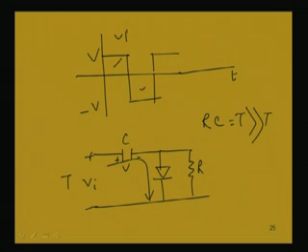Now, in the other half cycle, the negative half cycle, what will happen? In the negative half cycle, this point is negative, this point is positive. Now, this was already V, now again a V. So, across these 2 points, if we consider this voltage minus plus, it will be twice V, and this diode is biased by a voltage twice V with polarity, this is negative, this is positive. So, it is reverse biased.